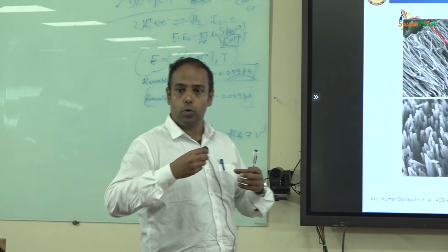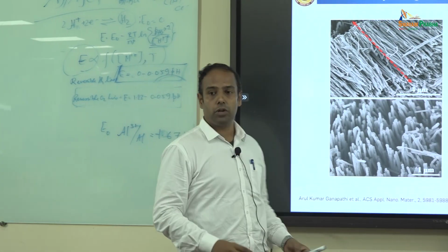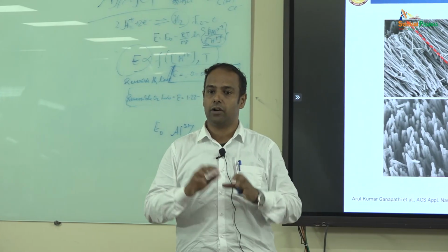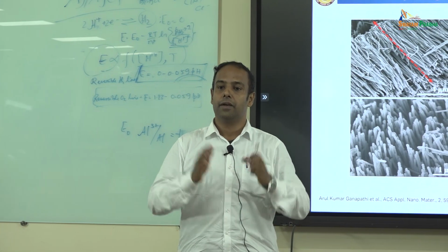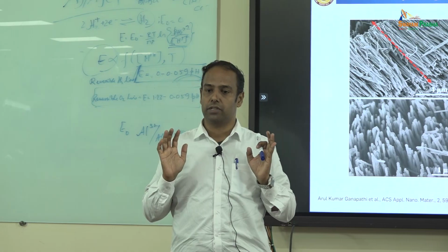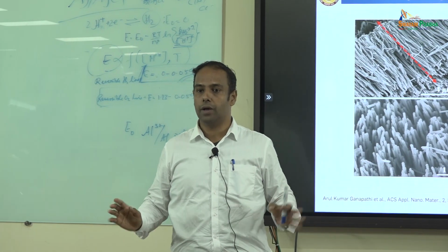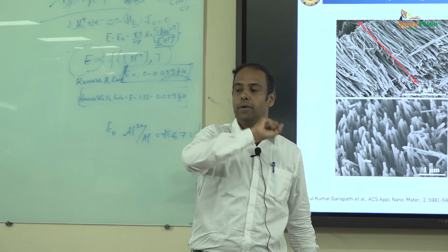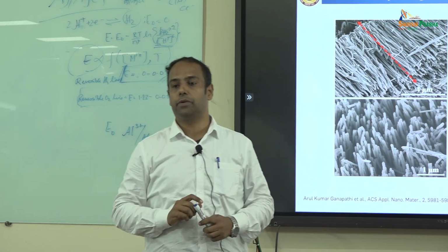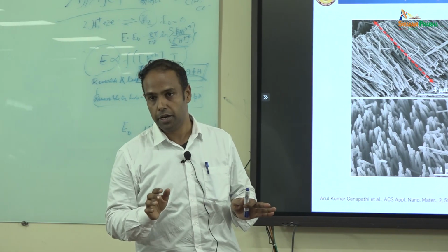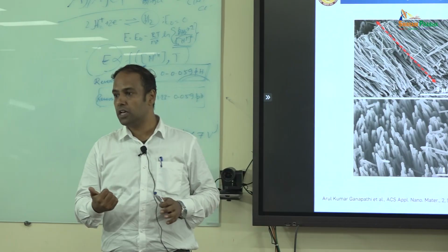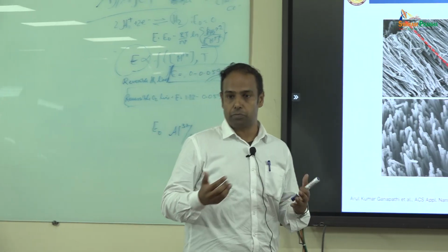Now, what I need to do, if I have to get these wires out, I have to identify the region where copper remains immune, or copper becomes a copper oxide, but alumina should dissolve. Again, I will go back to the Pourbaix diagram, identify at what conditions and potentials I can achieve it. So, this is one way you use the Pourbaix diagram from a research perspective.